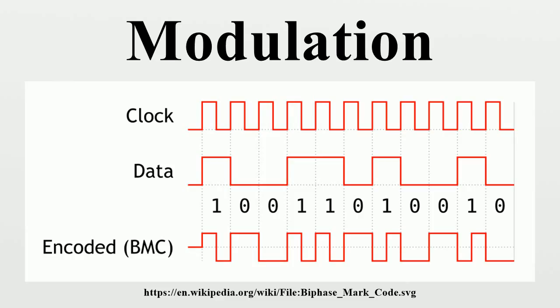Equalization filtering, for example a matched filter, compensation for multipath propagation, time spreading, phase distortion and frequency selective fading, to avoid intersymbol interference and symbol distortion. Detection of the amplitudes of the I and Q signals, or the frequency or phase of the IF signal. Quantization of the amplitudes, frequencies or phases to the nearest allowed symbol values. Mapping of the quantized amplitudes, frequencies or phases to code words. Parallel to serial conversion of the code words into a bit stream. Pass the resultant bit stream on for further processing, such as removal of any error-correcting codes.